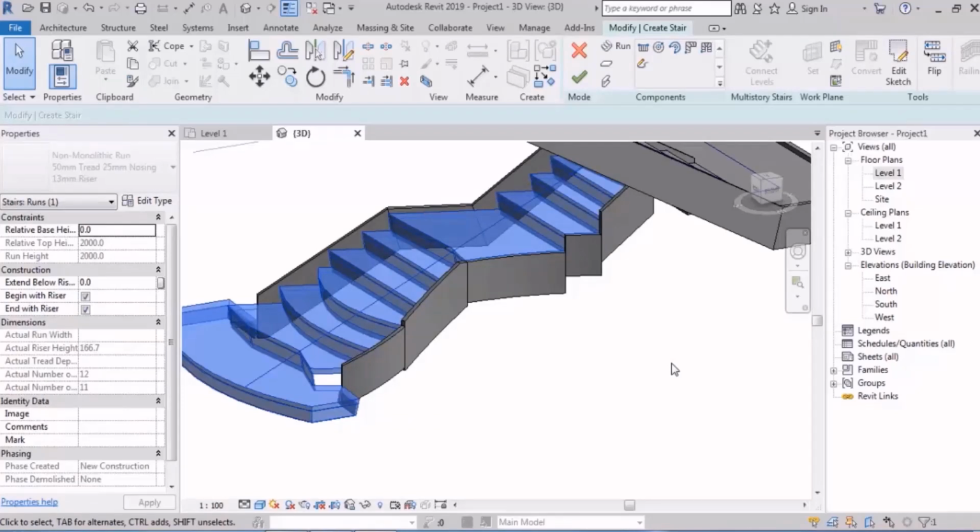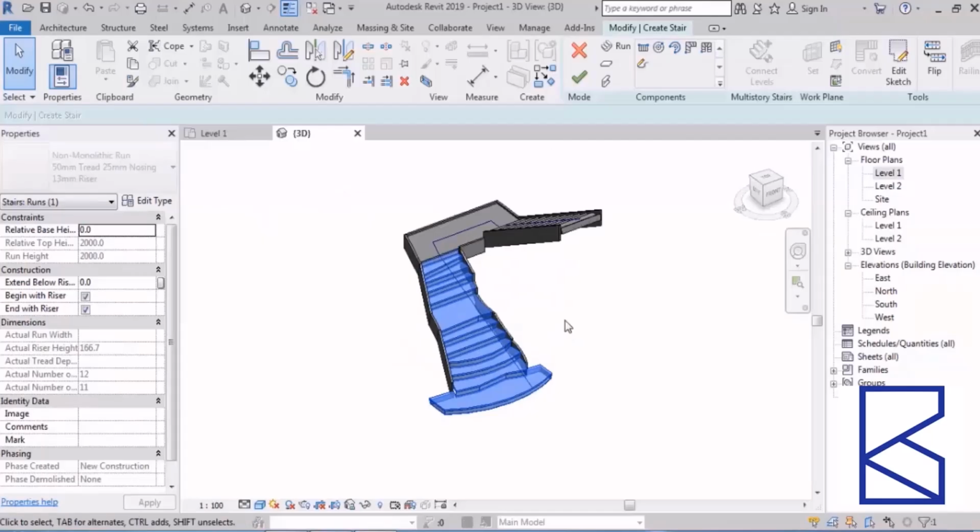All right. Now I want you to do something, and that's to draw 15 kinds of different stairs, but start from the simple ones. For example, at first edit the boundary and the risers a little, then go for those errors: what should we do if we create a weird form? If there's an extra riser, what should we do if the unjoined message comes? And all that. So practice this part very well because this part was really important.